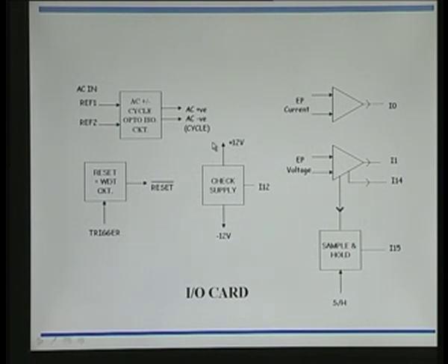And here comes the IO card. There are basically 3 cards, one is the IO card, as well as where the signal conditioning will have to be done, and it has electrostatic precipitator current. This is the analog op amp you have to use. You have to use a differential mode, a 2-stage amplifier you can have. And this first stage is for CMRR adjustment, so unity gain for that matter, and so is the case here, except that this will be sensing the actual current.